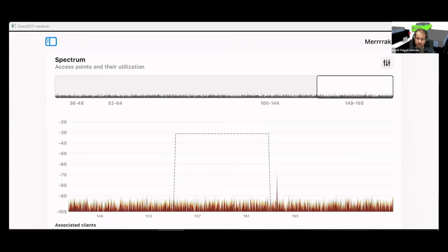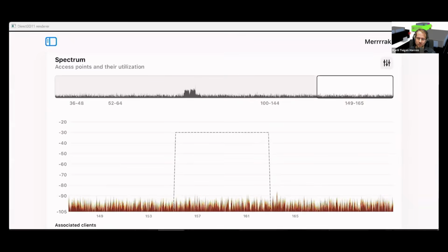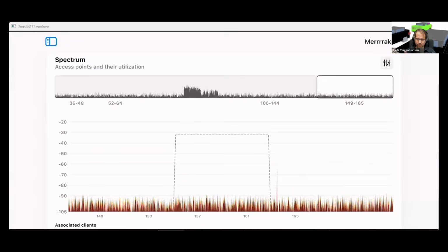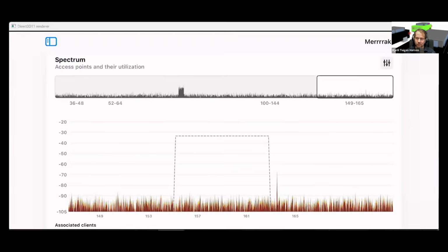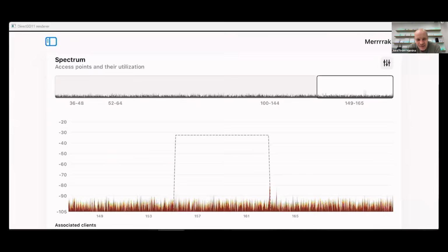Julio said that using FFT or using a single ADC, 12-bit, 80 MSPS, megasamples per second for all those nerdy people out there, instead of having a typical voltmeter that you're tuning and measuring one little bin at a time, coloring one little slice every time, you just take 1024 or 2K, 2048 points and paint it, and then you paint back. So you're like a super fast Bob Ross sweeping the band. Then you can see more, but then I can disconnect this and put it in the chamber.